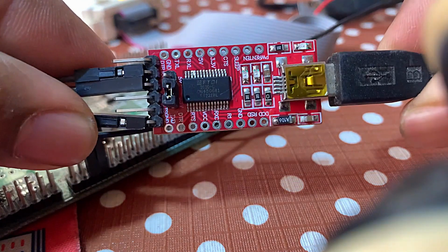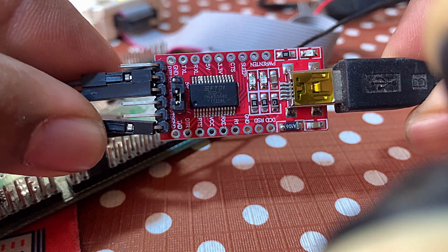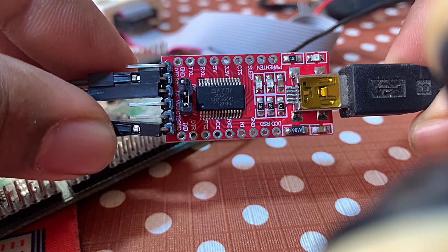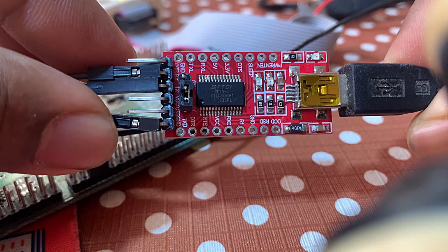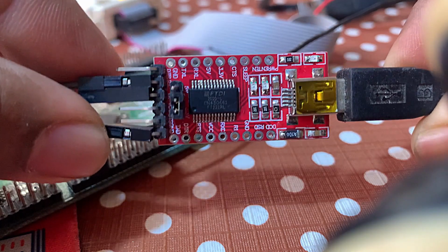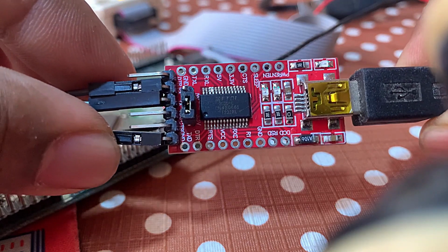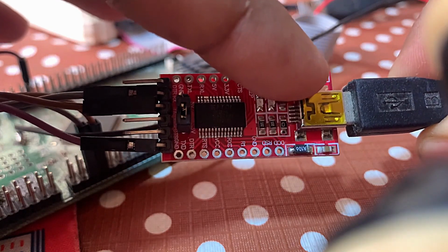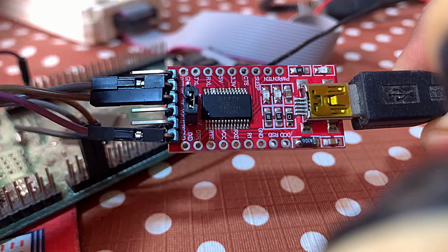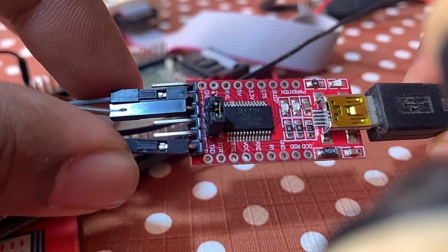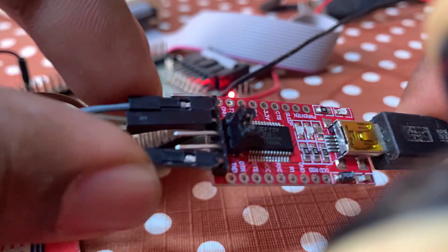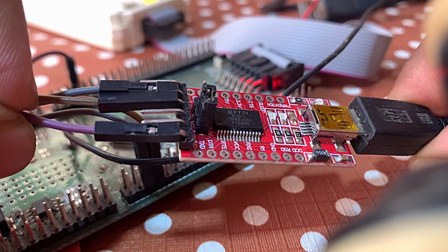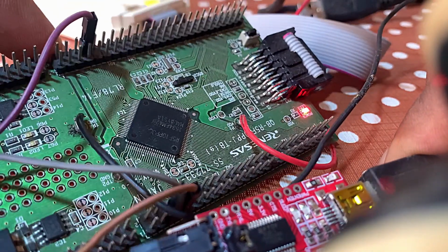So you can see this is the USB to TTL converter that I am using for transmitting the data from my microcontroller to the PC serial terminal and from the serial terminal of the PC to the microcontroller serial port. This TTL converter will help us to convert the high level signal from the PC USB port to the microcontroller level signal. In these terminals, we are just going to utilize only three terminals. One is the ground pin of this TTL converter, which is connected to the violet jumper wire, will be connected to the ground of the development board.